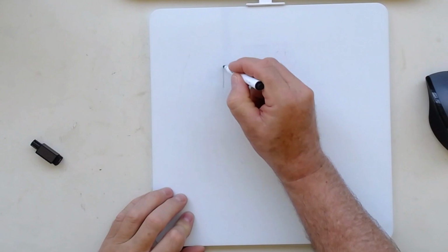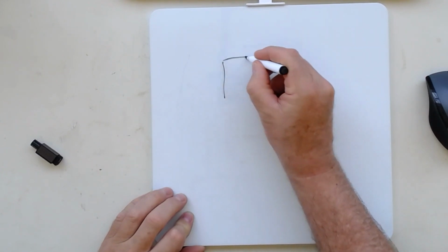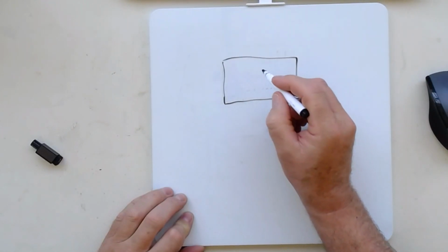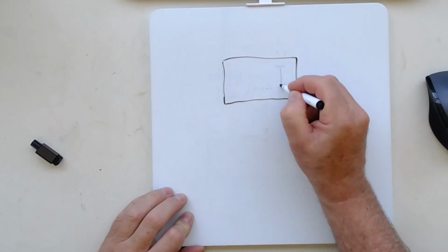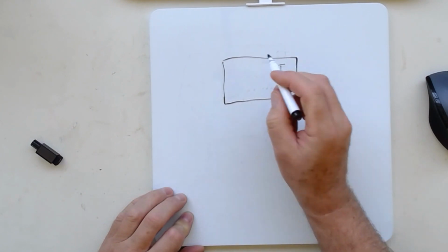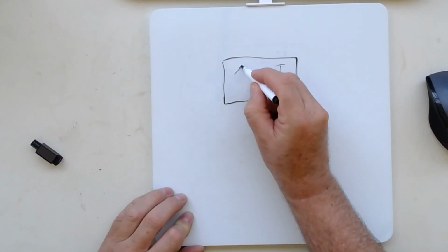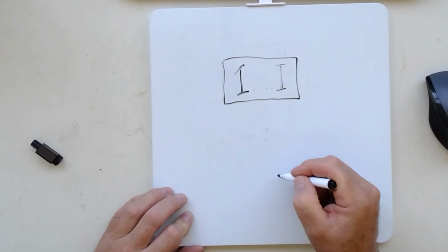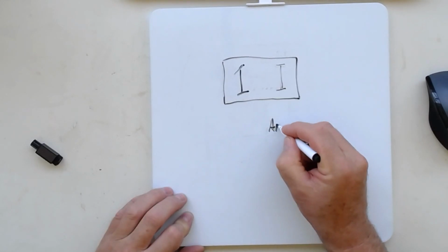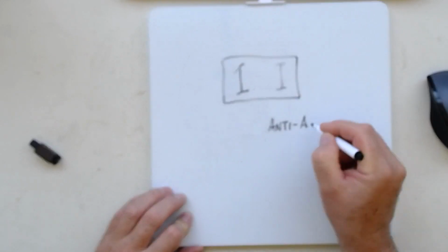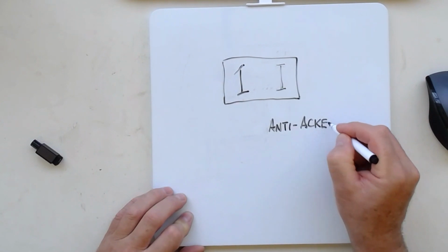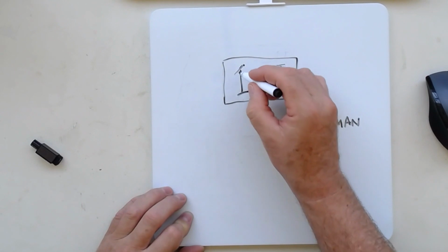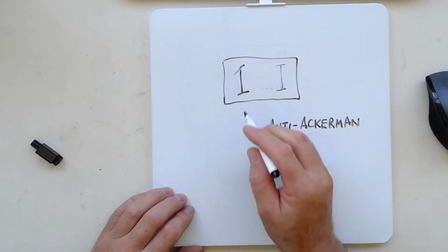Is everything Ackerman steering? No, but nearly everything. I'm not even sure I can draw this, but apparently on race cars, it's common to have what's called anti-Ackerman, where the outside wheel turns tighter than the inside.